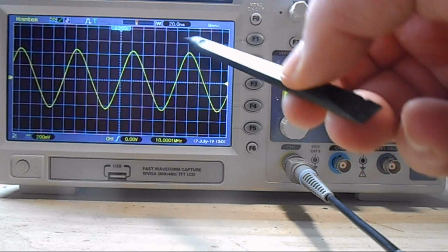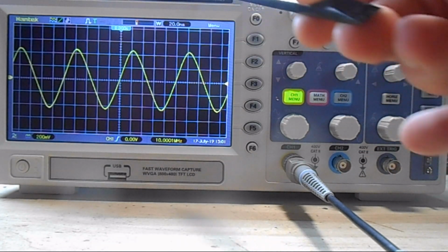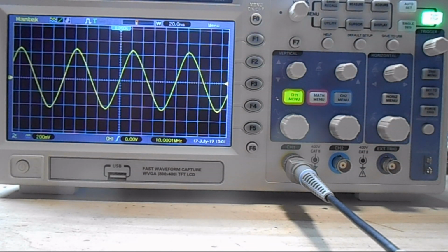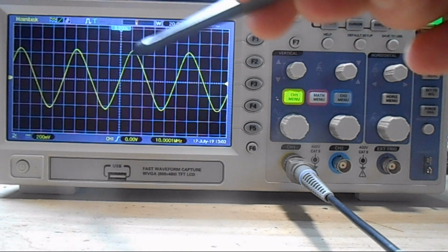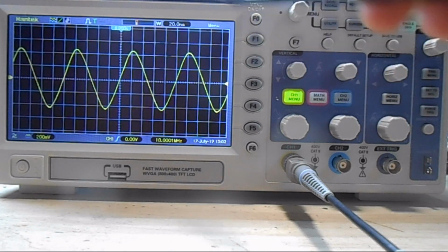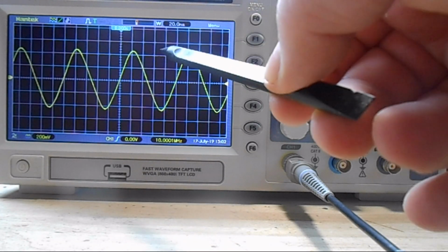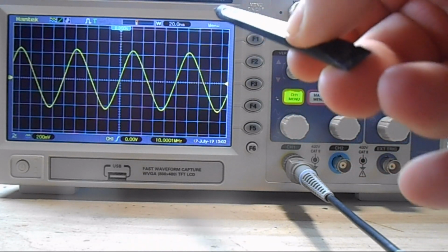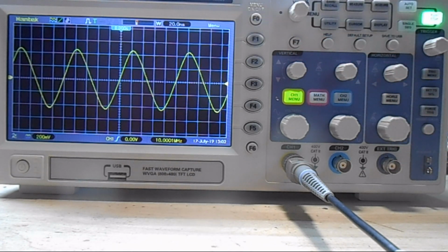Okay, now that we've cleaned that up, let's talk about sample rate. A digital scope samples a signal so many times per second, million times per second, in this case, a billion times per second, all right? And then it has to convert that sample, store it, and display it. The stored signal is visually reconstructed here. We've got billions of dots here that the oscilloscope has reconstructed to show us our signal. And that's the sample rate: how many times per second the oscilloscope is getting in there and doing that.